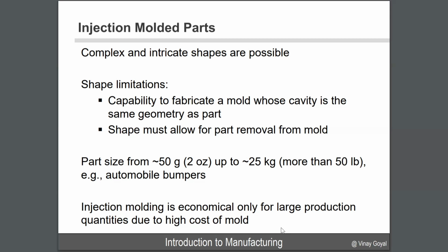So, for example, automobile bumpers. By the way, automobile bumpers are not there to protect you in a car accident. The plastic that's outside is a feature, but what's really protecting you is the reinforcements behind them. These automotive bumpers are manufactured using injection molded parts. The reason these are great is that they are quite inexpensive and economical, and number two, you can produce them at very high rates. And the cost of the mold is not as bad.